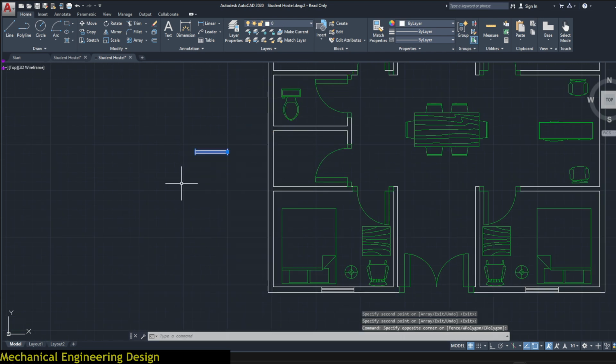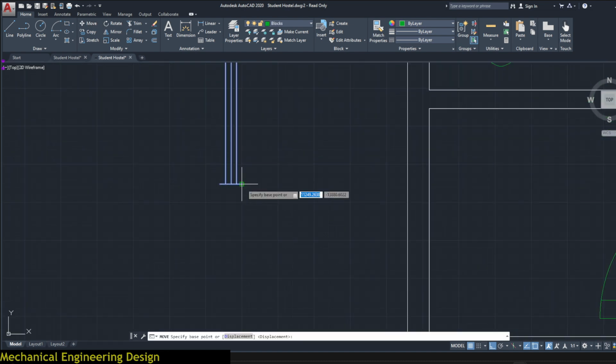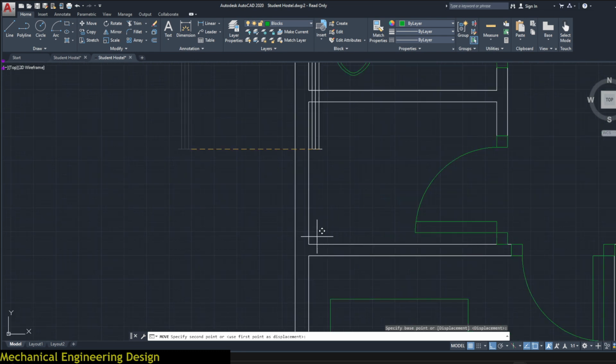You also need another one here. Enter and rotate. Rotate it 90 degrees. So just turn on auto to make our work easier, like that. Select, move, identify this corner, turn off auto mode, come here and drag it upwards to ensure it's at the midpoint of the bathroom.